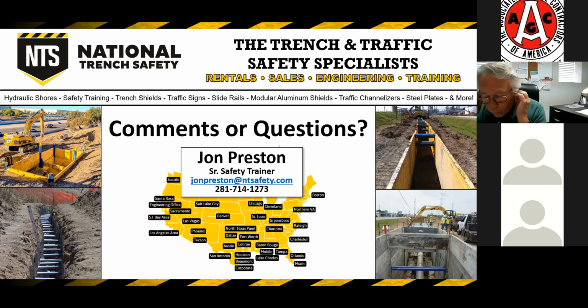While we're getting some questions, I have one more point I'd like to bring up that sometimes is a question that people have, and that is whenever someone is sloping or benching, a lot of times they wonder if the adjacent area still comes into play. And the answer is in subpart P in Appendix B, OSHA does make reference to surcharge loads when sloping or benching.